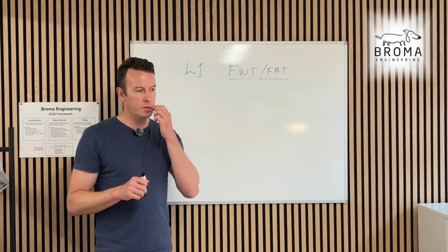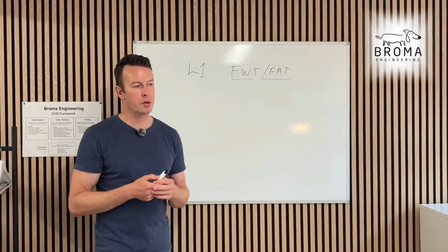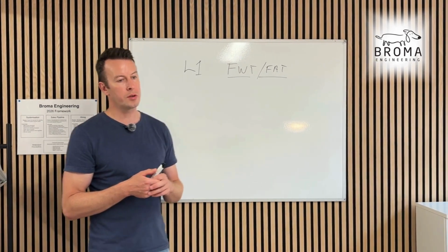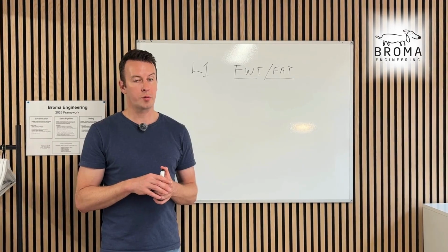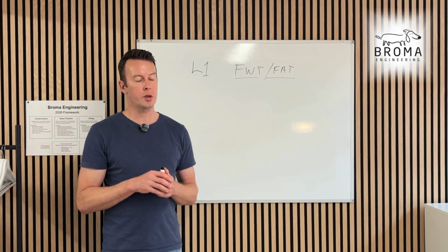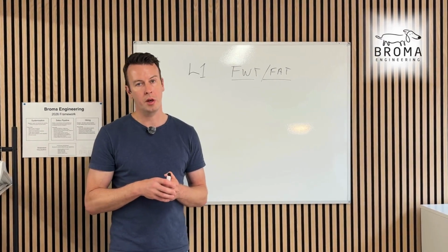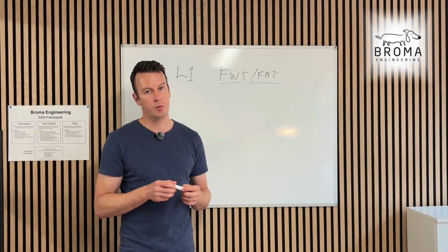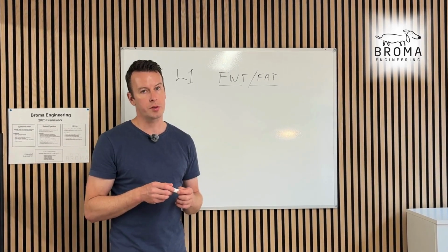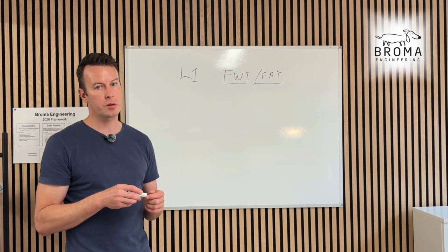Okay, just back to level 0 or pre-construction and level 1 and getting on to level 2. We need a technical submittal approved, so we need a specification. Usually AHUs will be OFCI, sometimes not. It's becoming more common that they're CFCI, but usually in the past they've been OFCI, so that's owner furnished, contractor installed.